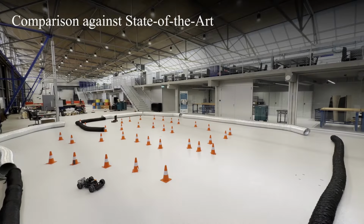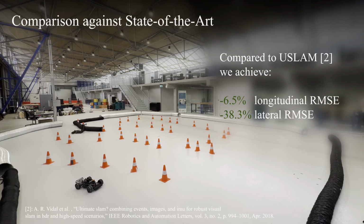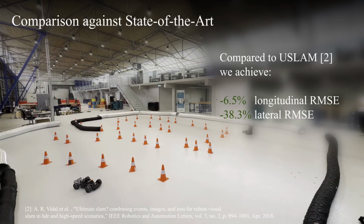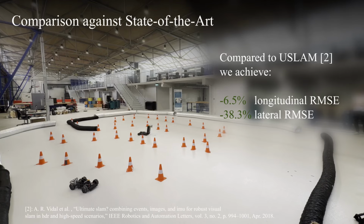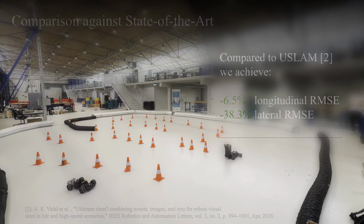Finally, we compare our approach against the state-of-the-art Event-VIO method using a Vicon motion capture system. Our results show that measuring velocity directly from the optical flow on the ground outperforms VIO, especially for lateral velocity estimation, which is crucial for detecting unstable vehicle conditions such as tire slip.